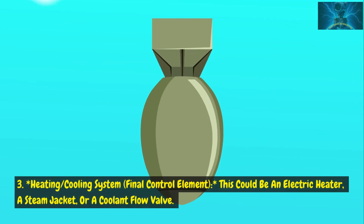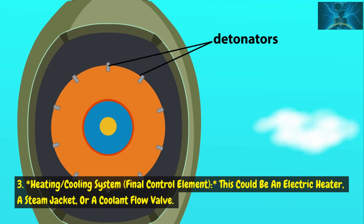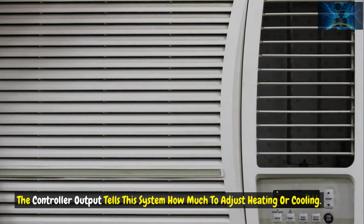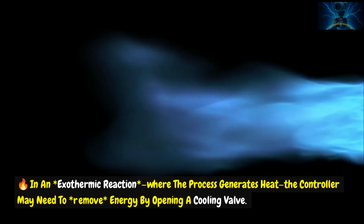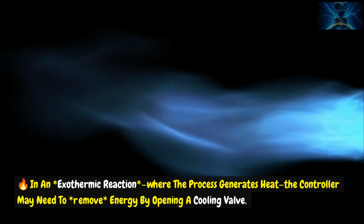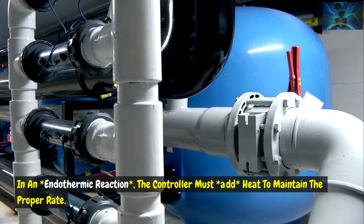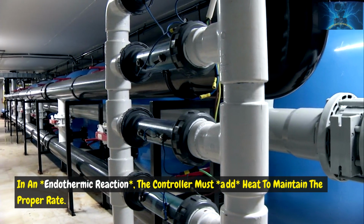3. Heating-cooling system, final control element. This could be an electric heater, a steam jacket, or a coolant flow valve. The controller output tells the system how much to adjust heating or cooling. In an exothermic reaction, where the process generates heat, the controller may need to remove energy by opening a cooling valve. In an endothermic reaction, the controller must add heat to maintain the proper rate.